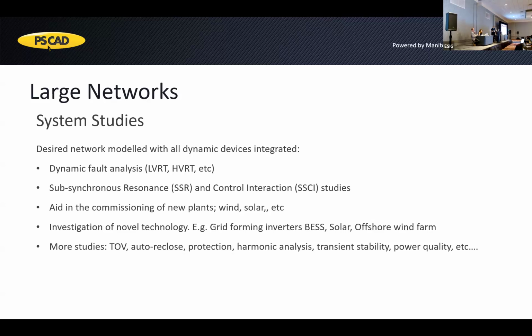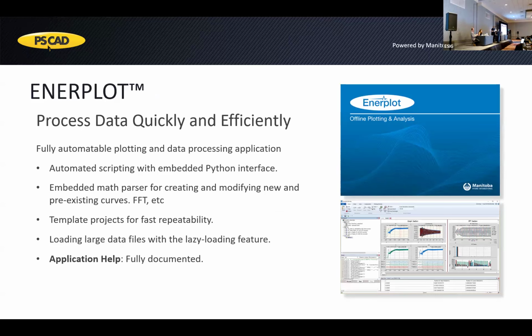Now with this, you're going to have a lot of data that comes from PSCAD. And so what MHI has also developed is a plotting tool that works in the offline environment that we call Enerplot. There's a lot of features to Enerplot, and you can manipulate and track all of your data for any type of analysis. It does come with automatic scripting using Python as well as recording. It has embedded math functions, so you can manipulate your data as you see fit. You are able to template projects for any type of fast loading and repeatability.